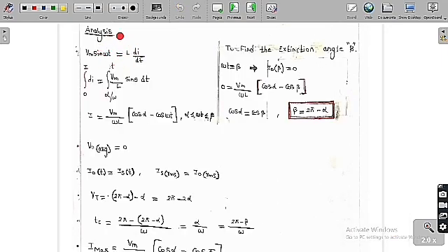So now we are going to do some analysis for this circuit. See, when the thyristor is on, we can say that the output voltage is equal to the source voltage. Therefore Vm sin omega t is equal to L into di by dt. If I do the rearrangement, I am going to get di equal to Vm by L into sin theta dt, where the current goes from 0 to I, and the time is from alpha by omega to t.